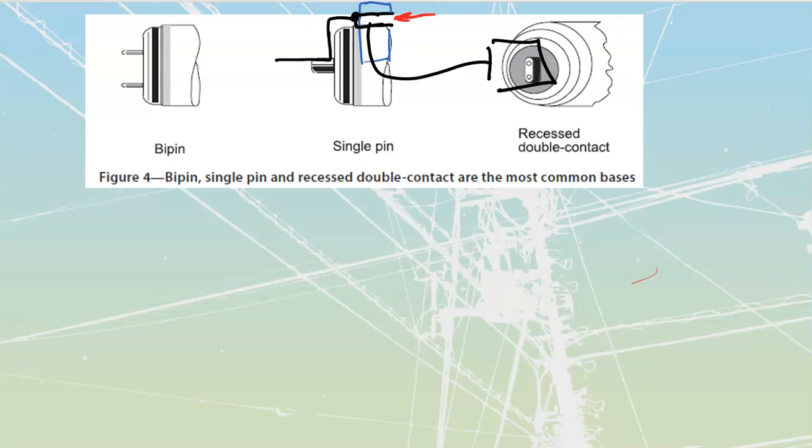The other one was to place an incandescent in the room. If you ever run into an area that has moving machinery and there's some fluorescence and there's an incandescent inside there, there's a very good chance that that incandescent was put in there to deal with stroboscopic effects, because the incandescent is literally heating that tungsten to the point of glowing. So that's going to maintain that.